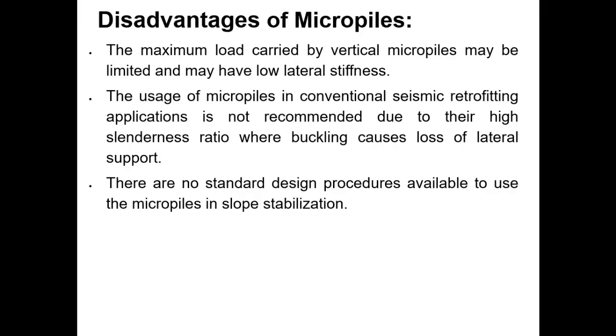The disadvantages of micropiles are that the maximum load carried by vertical micropiles may be limited and they may have low lateral stiffness. The usage of micropiles in conventional seismic retrofitting applications is not recommended due to their high slenderness ratio, where buckling causes loss of lateral support. There are no standard design procedures available to use micropiles in slope stabilization.